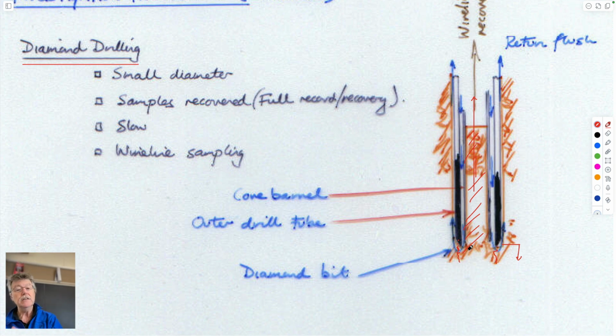You can look at the fractures in it, because you know those fractures are the things that water is going to be traveling in. You might look at staining on those fractures to see if water is actively traveling in it. And it would give you a demarcation again between different stratigraphy that's present in situ. And this is really for rock only.